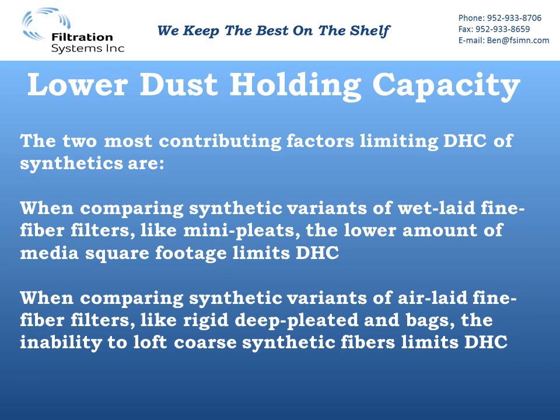So at the end of the day, really all you're getting with synthetic medias is something that's cheaper when you first purchase it. But the long-term impacts of it are pretty horrible when you're not getting a filter that stays at the efficiency that you're purchasing it for, and you need to wind up replacing them more often than you would a fine fiber media. The initial difference in cost is far outweighed.